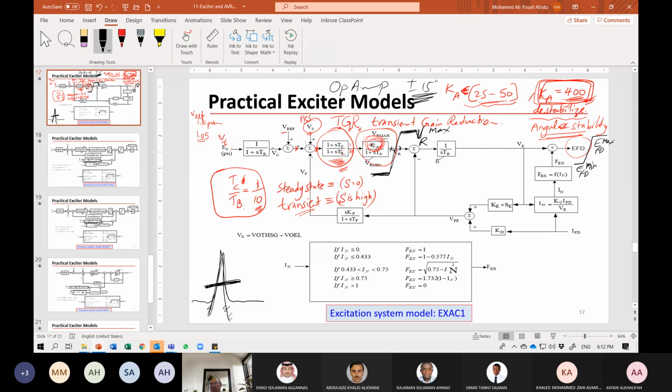So this is the excitation system. Definitely, this winding needs a maximum voltage that cannot go beyond, for example, 300 volts. So this is the limit. Is it clear? You are not allowing this voltage to be more than 300, otherwise you may have damage here. Is it clear, Ayub? Yes, Doctor.